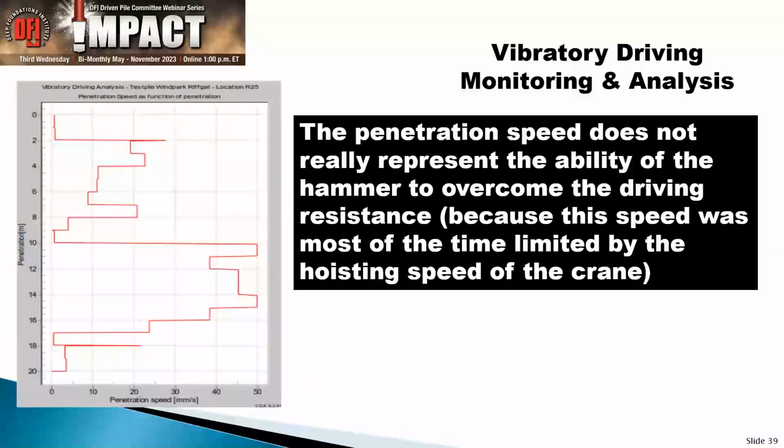So then we look at the penetration speed and start to figure out what's happening. And what's happening there is kind of weird, because initially, in this top layer here, you see that we would go down and back up again quite a bit. What is happening here? Well, it brings me back to what I said earlier. The penetration speed is not really the same thing that you have when you drive a pile with an impact hammer, because now I'm also dependent on how much hook load, the uplift load, I have in my winch.